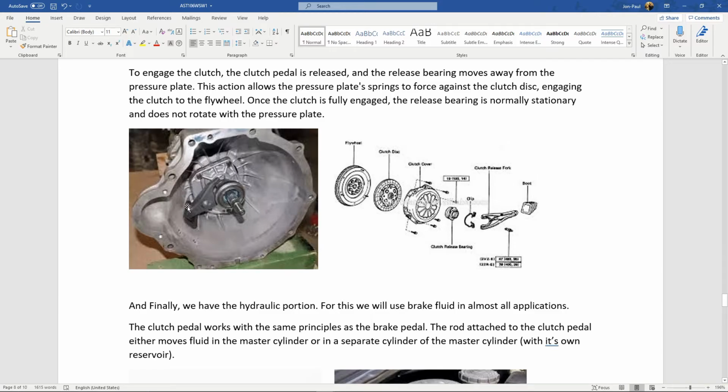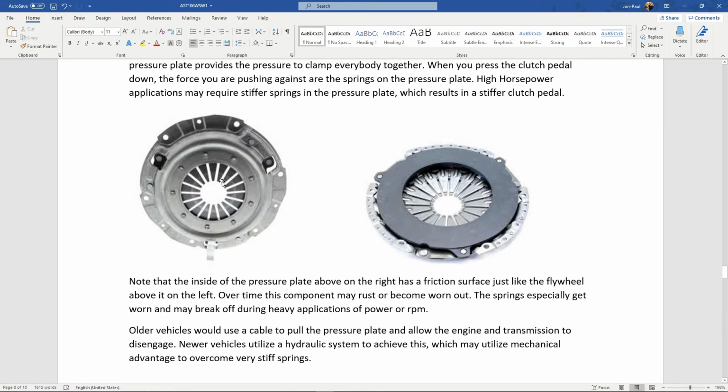It'll be in this bell housing making noise. Imagine we take this pressure plate and break half of the fingers off. That bearing will probably find its way in there and get locked up and jammed, right? It'll probably get pushed further than it's supposed to go.